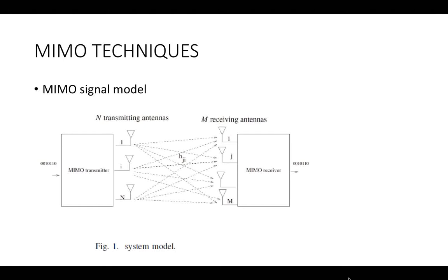Generally, there are three categories of MIMO techniques. The first aims to improve the power efficiency by maximizing the spatial diversity. Such techniques include delay diversity, space-time block codes, which we also call STBC, and space-time trellis codes. The second class uses a layered approach to increase capacity.